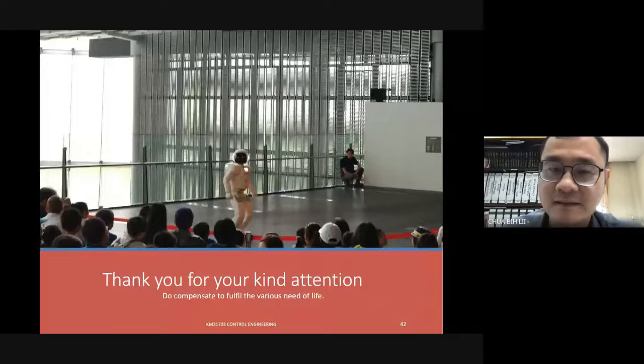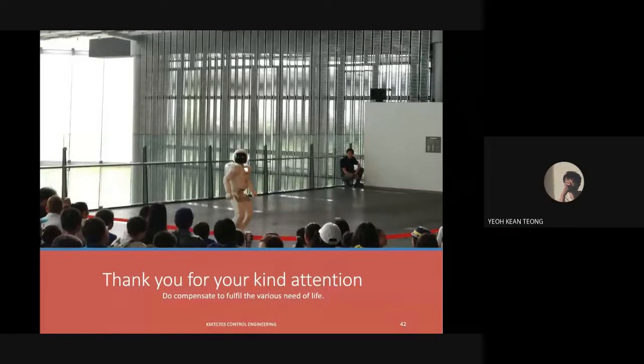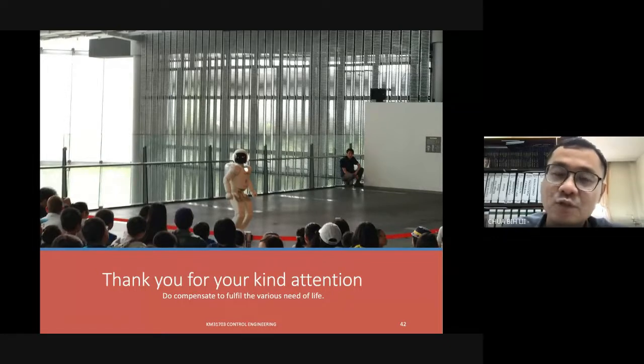Doctor, can you hear me? Yes. So the purpose of the root locus and Bode plot magnitude is to make the system more stable, right? Yes. First, for sure we want to make the system more stable. The second thing is we want to improve the performance. When we do the compensator, we always try to reduce the steady state error if there is any, and then we may also want it to respond faster, to reduce the settling time and the peak time.